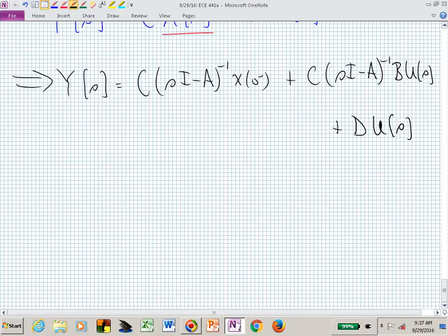If I want the transfer function, how does that simplify this expression? What have I done before when I'm just wanting the transfer function between the input and the output? I can ignore the initial condition. And I want now to find that transfer function, I'm trying to find TF, which means that the terms that involve the initial condition I'm going to neglect.